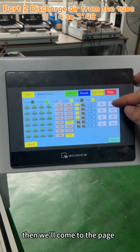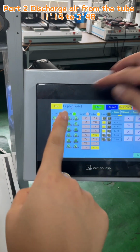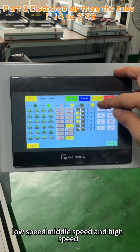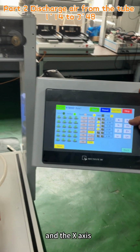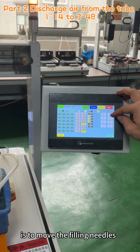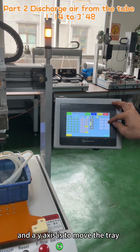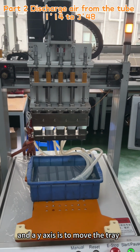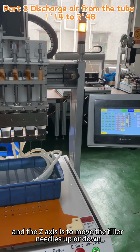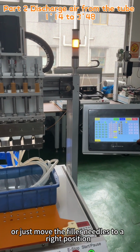Then we'll come to the page to adjust some details of the filling parameters. We can choose the machine move speed: low speed, middle speed, and high speed. The x-axis is to move the filling needles to the left side or right side. The y-axis is to move the tray backward or forward. And the z-axis is to move the filling needles up or down. And we'll just move the filling needles to a right position.